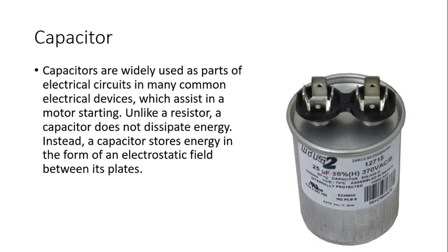Capacitor. A capacitor is something that helps assist the start of a motor, like a compressor or a fan motor. They're used in all kinds of motors. Everything you probably have in your house has some bit of capacitor in it. Now, I'll let you know that's a little confusing. That's all with single-phase motors. 3-phase motors do not use capacitors because there are 3 actual phases. It starts easy without a capacitor.